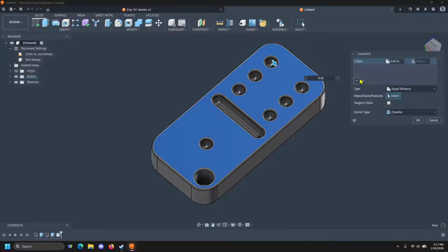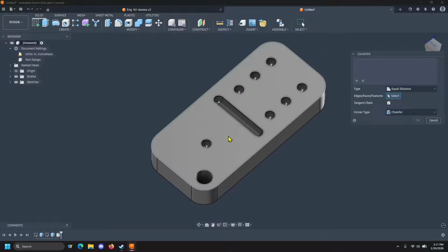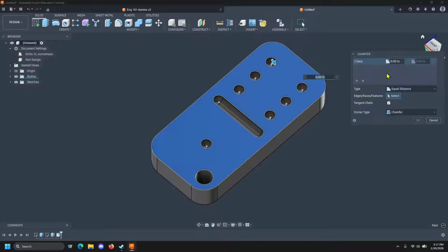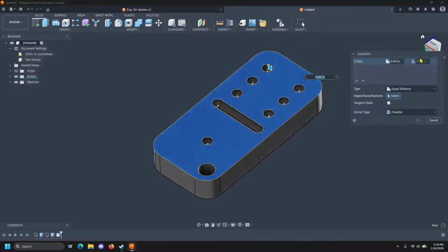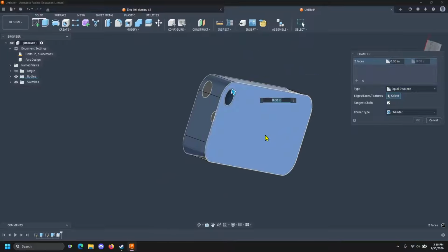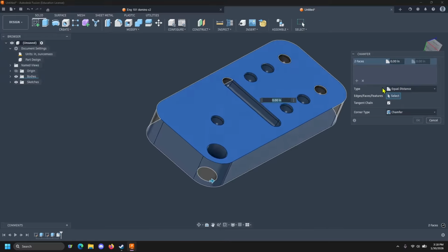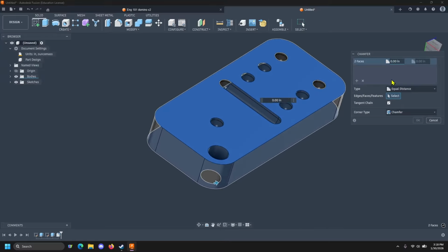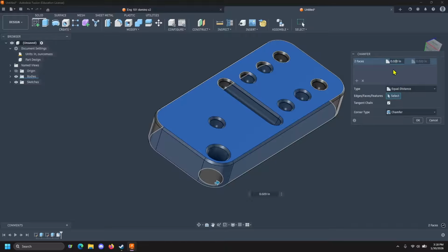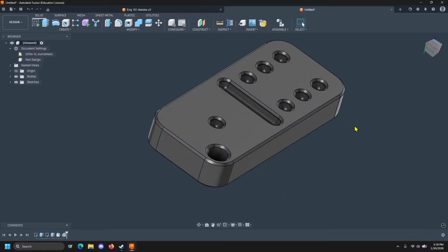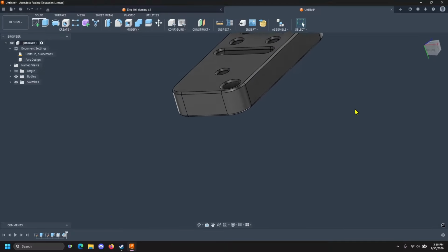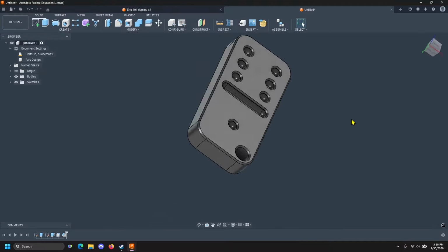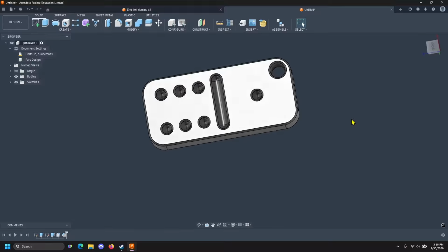But what we're actually going to do, we're going to remove the selection step because I forgot the other side. So we're going to select both sides. So you can rotate your object over to the other side, and we're going to select this bottom face as well. And now I can actually set this to be our 0.02 inches. And I'm going to press OK. And voila. Now our domino looks complete. We got all those chamfers, we have those fillets, and it's very pretty.